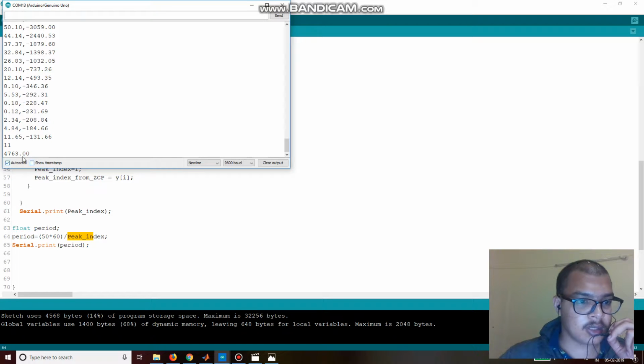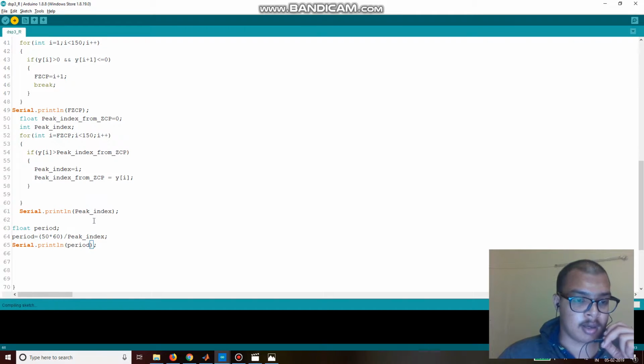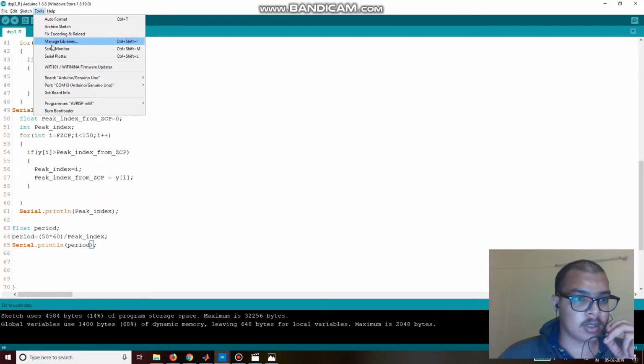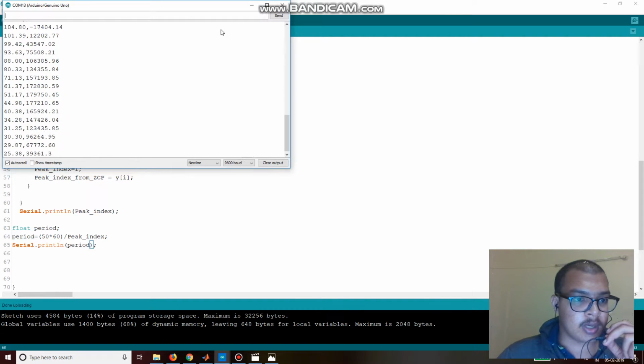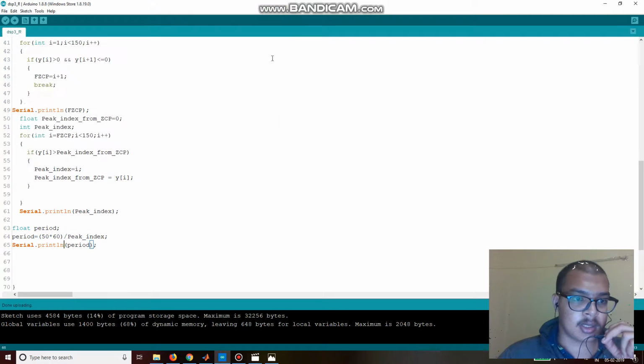It caused an error due to a mistake. So here we would be using the print line, so it would change the line for the next parameter. In the next line it would print the heart rate of the required function, and then we run it again, and we get a value of 63. So this concludes the PPG signal part of the experiment. Our heartbeat was recorded as 63.